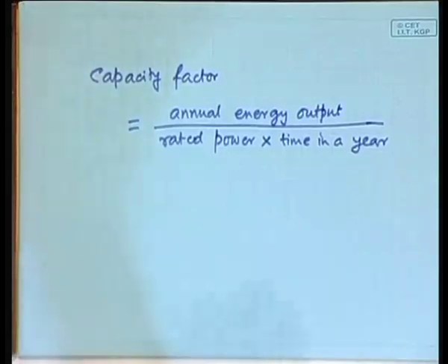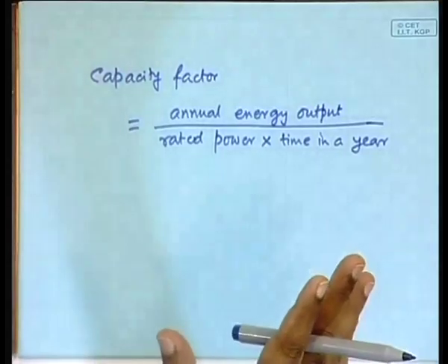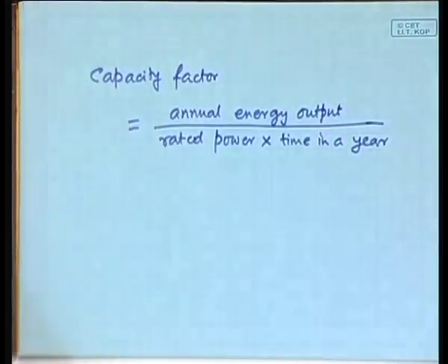You may have heard of the term load factor in case of power plants. What is the load factor? It is essentially a similar concept: out of the whole capacity that is available, how much is being utilized? So a thermal power plant, supposing it is rated at 200 megawatts, if you had produced power at this 200 megawatt level all through the year, then you get some amount of energy. Now that being in the denominator, in the numerator is how much energy you have actually generated out of the plant, that is the plant load factor.